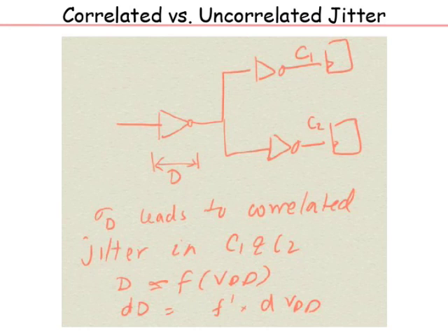But that could be very conservative, because if both C1 and C2 are, say, completely correlated, then relatively there is no effect. The jitter is completely gone, because they are both moving together up and down, so it will not affect the timing constraint. So that is basically all I'm saying for timing constraint.